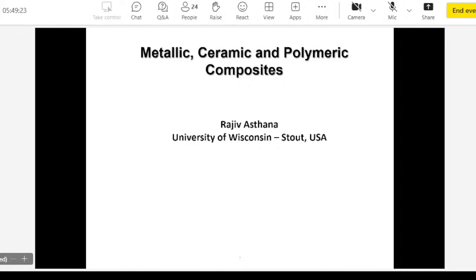So just to get started, let's consider wood. Ordinary wood is a composite, a natural composite, not a man-made composite, obviously, but a naturally occurring composite. In a composite, you have at least two different chemical phases. One could be fiber or particles, and the other phase could be a continuous phase, the matrix phase. In the case of wood, the fiber is actually the chemical cellulose. So that's the fiber, and then lignin is called the matrix material.